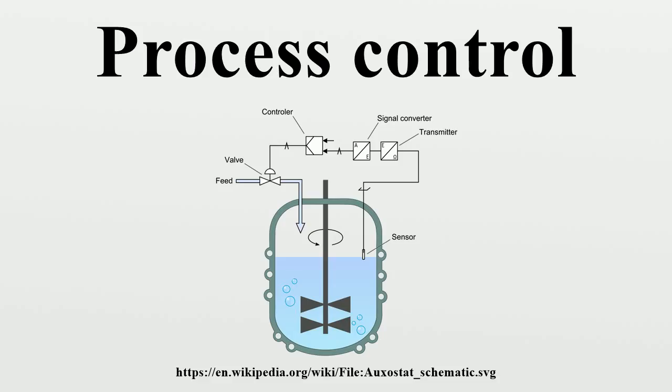A thermostat on a heater is an example of control that is on or off. A temperature sensor turns the heat source on if the temperature falls below the set point and turns the heat source off when the set point is reached. There is no measurement of the difference between the set point and the measured temperature and no adjustment to the rate at which heat is added, other than all or none.